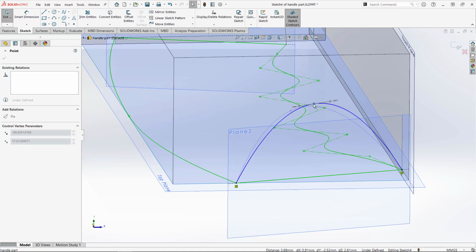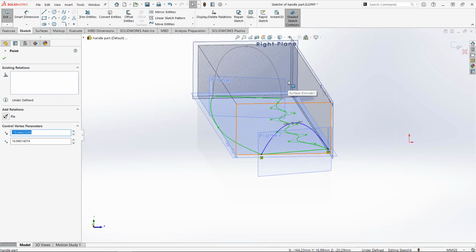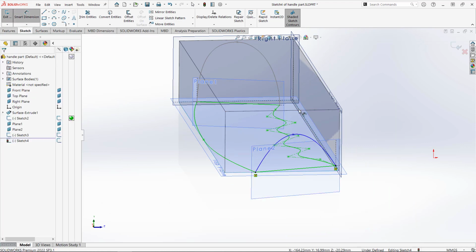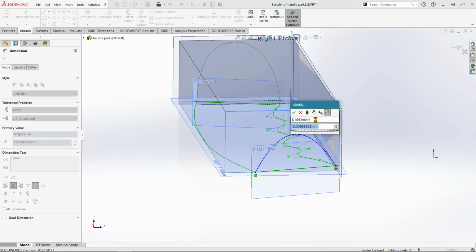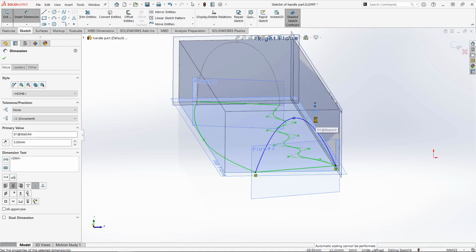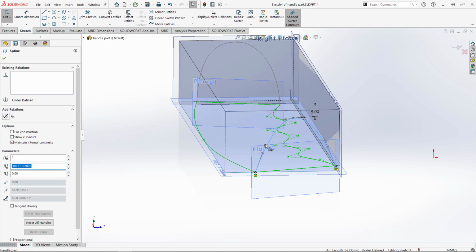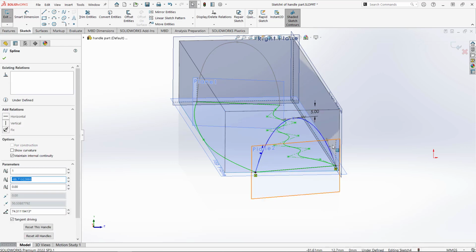So now we're going to edit the top point here. I think on this end we'll make it indented from the top of our size limit box. I think we'll set this at 5mm, like that. And then I'm going to click on the spline, and I'm just going to quickly drag the spline control handles, or the spline drag handles, around a bit.